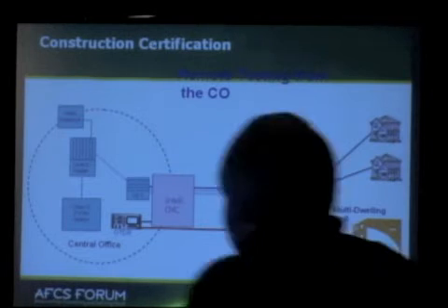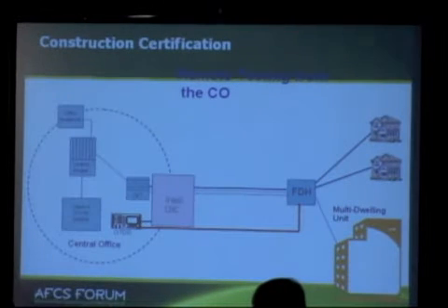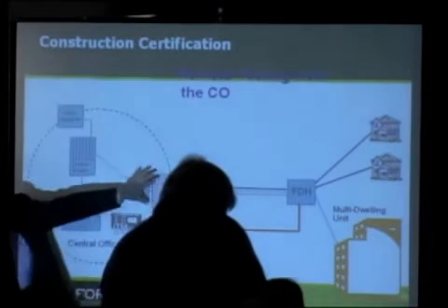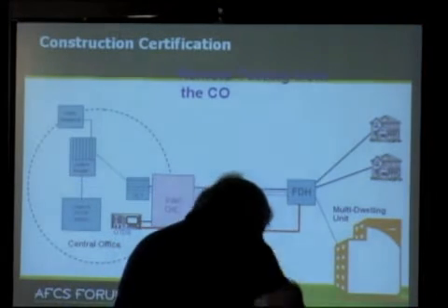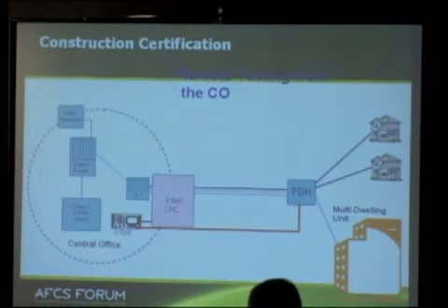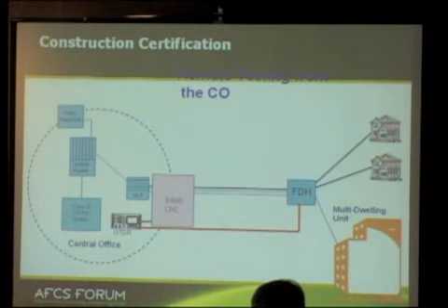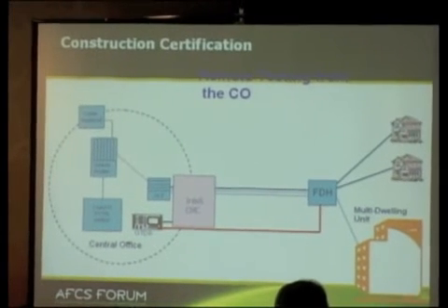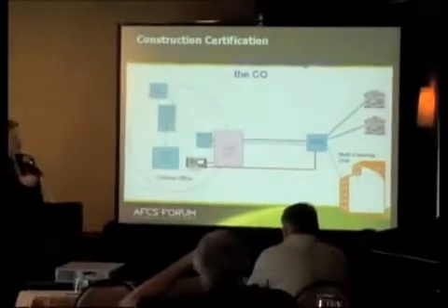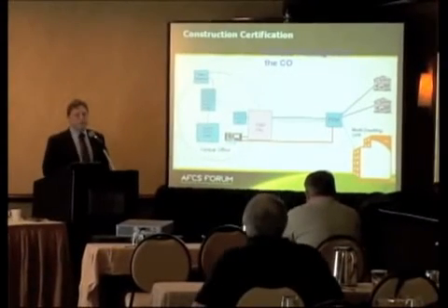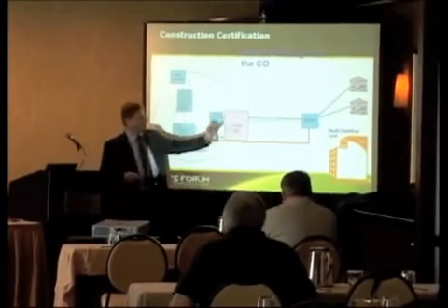We are supplying the access to the physical fibers, a device connecting all the fibers that will allow for the insertion of an OTDR test signal or burst and shoot the fiber and collect those data results. In this particular situation, we are on the subscriber side of the OLT. We have the ability to test the F1 segment of the fiber, which is defined here.